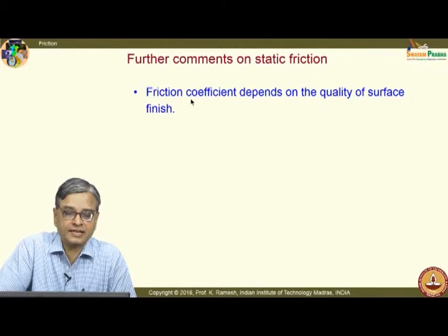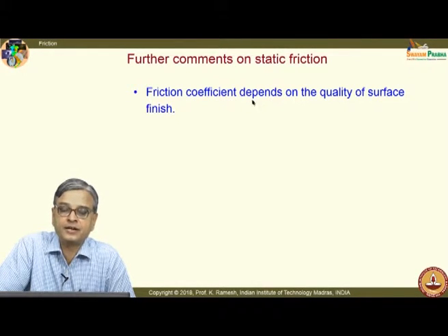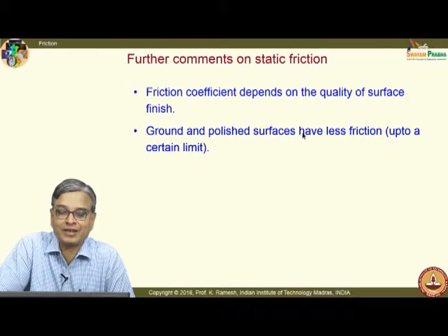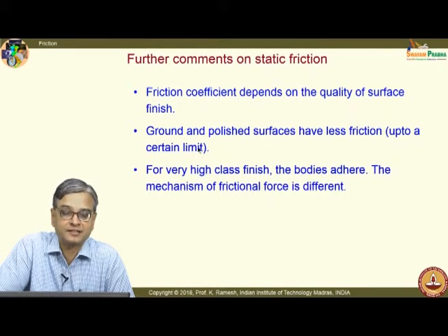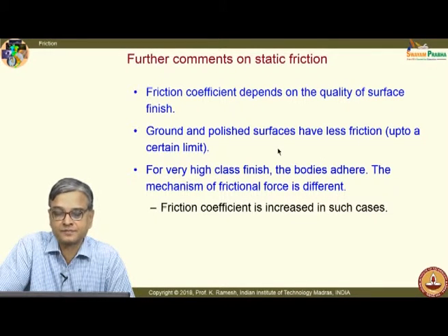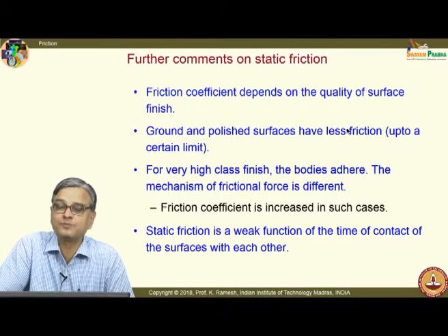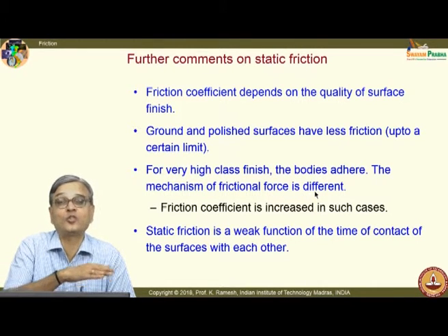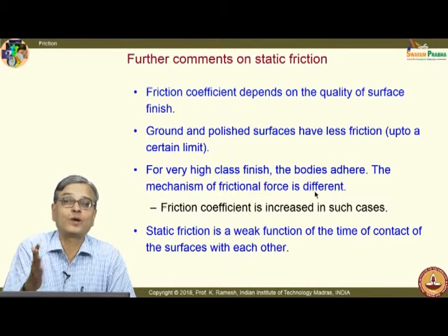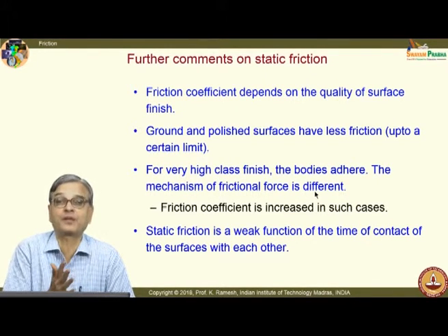And you should also recognize friction coefficient depends on the quality of surface finish. Ground and polished surfaces have less friction up to a certain limit. It is not that if I have a honing operation done on the blocks, which will leave a very smooth surface finish, for a very high class of finish, the bodies adhere. There the phenomenon totally changes. It is not engagement of micro projections, adhesion becomes predominant.